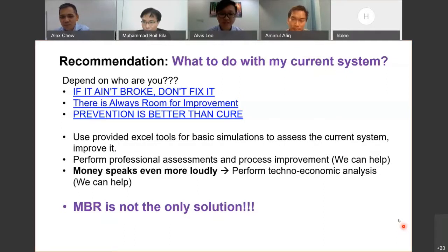Okay, Dr. Roy, I think there are the last three questions here. The first one is from Miss Li Hui Ling. She is asking whether using MBR can help reduce the hardness in treated effluent for reuse purposes. The answer is no. We cannot, because calcium and magnesium are in solution, and they are so small they will pass through the membrane pores. So the only way is to go to RO for reuse purposes, or maybe you can adjust pH to precipitate the calcium or magnesium, but relying exclusively on MBR is not possible.